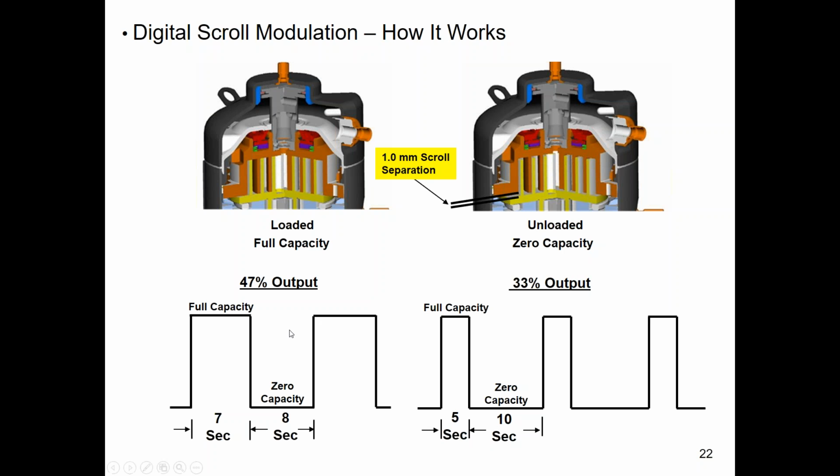You can't do it. The only thing, and we don't even put it in the manual, would be a concrete trench, if you will, and then put steel grates over the top so the pipe is exposed to the ambient temperatures outside. But you just can't bury the pipe. If you got a job with buried pipe, you need to find another route. There's no exceptions to it.